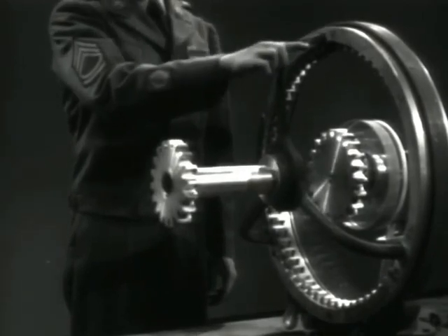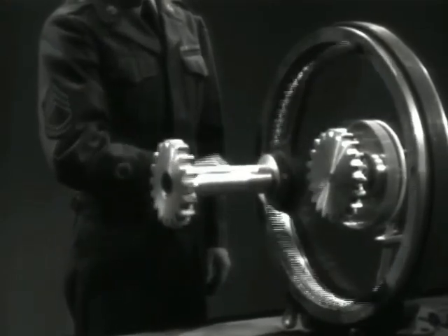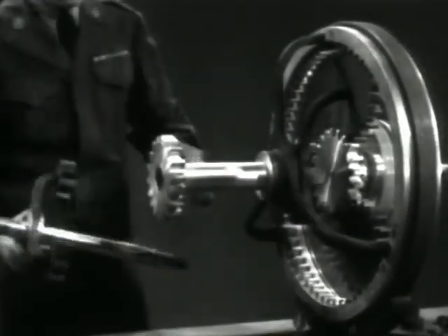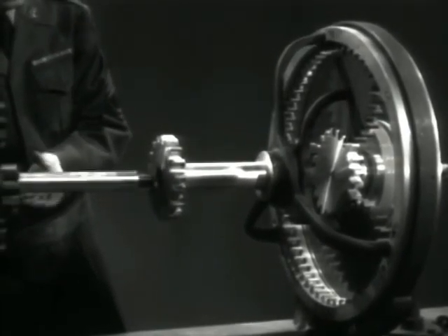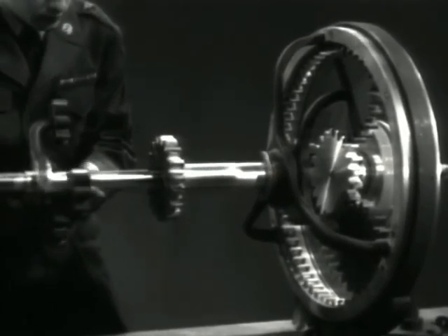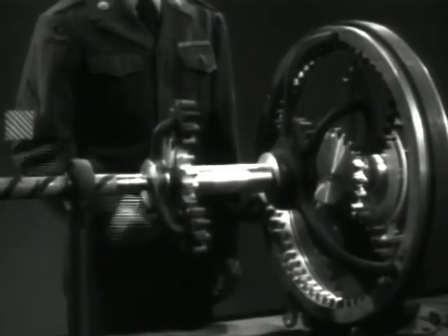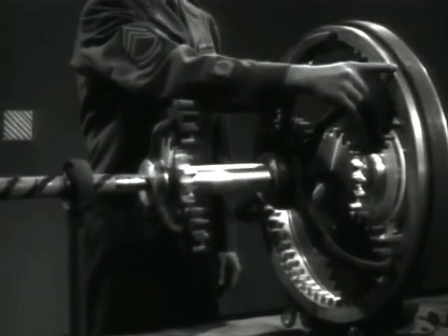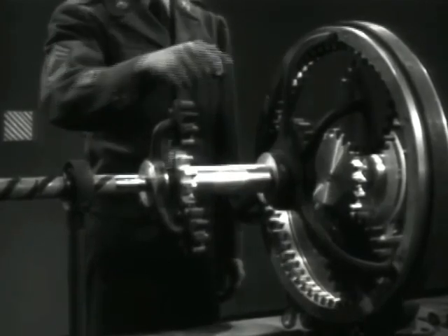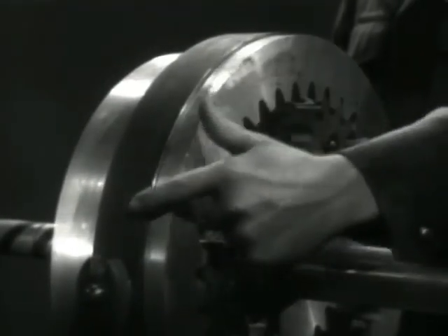The ring gear of the intermediate set is connected by this shaft to the sun gear of the reverse unit. This connecting shaft is hollow to allow the output shaft to pass through it and connect the planet carrier of the intermediate set to the planet carrier of the reverse unit. We have the planet carriers of these two units connected by the output shaft. And we have the ring gear of the intermediate set connected to the sun gear of the reverse unit. The next thing we add to the reverse unit is its ring gear, which can be held reactionary by a cone-type clutch.